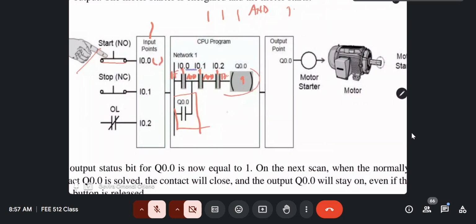That's why it's shaded. And as soon as it's logic 1, during a scan cycle, the processor will run through the entire rung. Once all the rungs have been exhausted, in this case we only have one rung, meaning the scan cycle has come to an end, then it updates the output to logic 1. The output module will take that logic 1, translate it to an electrical signal, which then helps to start the motor. But remember, it's because this guy here pressed.